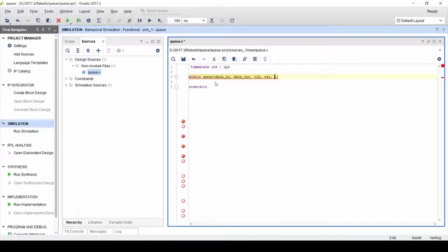But what happens if you have not checked whether the queue is full or empty? We are using pointers, right? Whenever this pointer exceeds the maximum capacity, for example if we use 3-bit pointers, whenever it exceeds its maximum limit, it again resets to the 0 value.